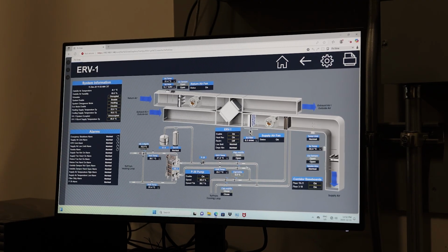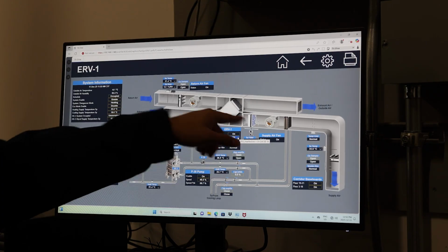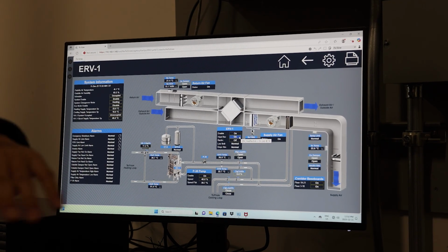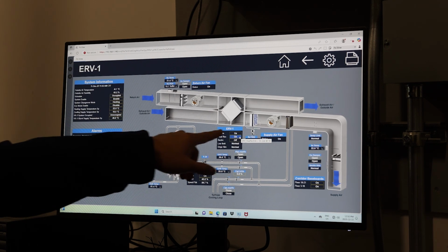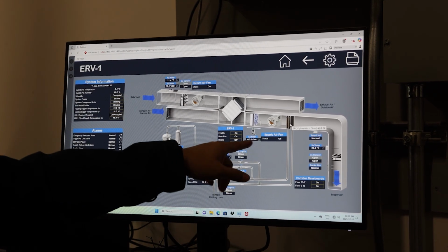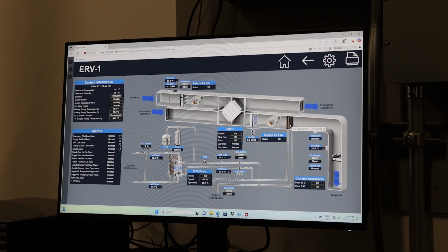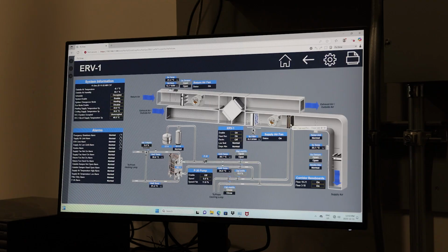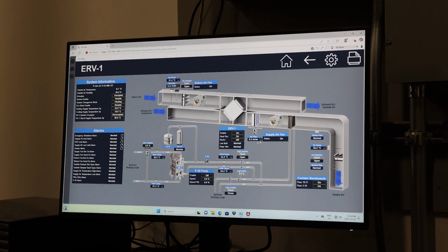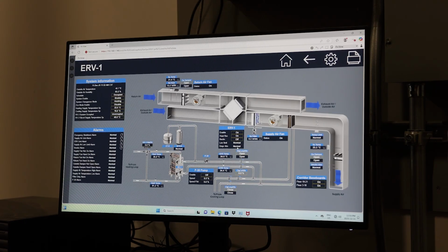Remember, because right now we are in the heat recirculation mode, the ERV internal damper will switch every 60 seconds. While that damper is switching, it affects the flow rate, because when that damper is closing, suddenly we will see this drop a little bit, right? And then once that opens, we will see pressure go up again. You can use that to tell whether the damper is working or not as well. And also if the damper failed, we will see a damper alarm on here.